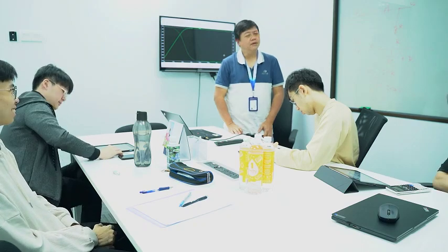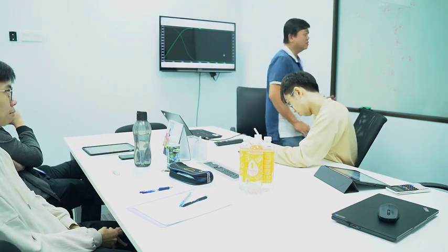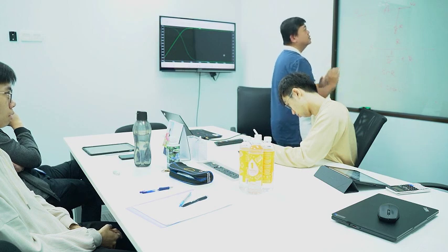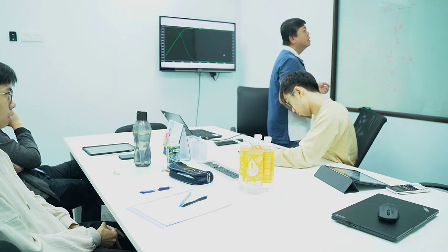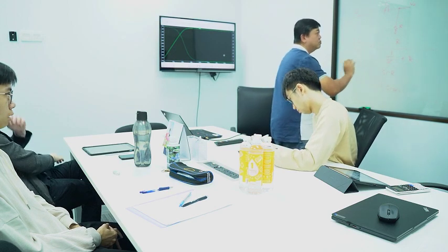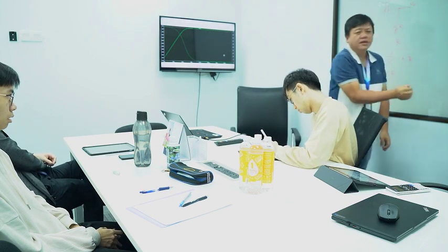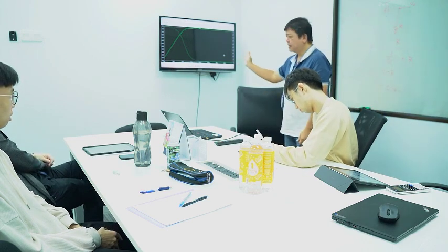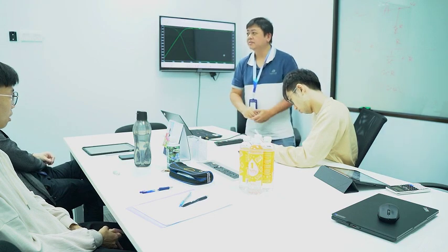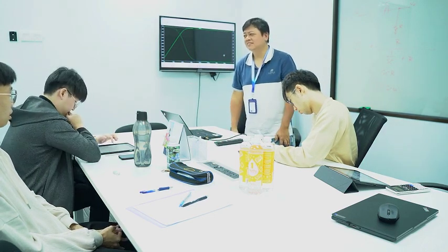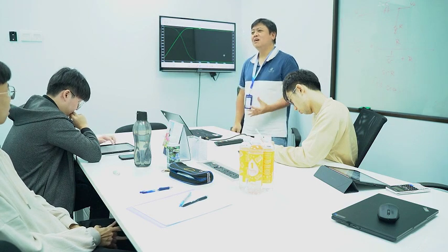But when you learn based on understanding, you derive the formula. After that, you know that a high pass filter has one zero and one pole, and you prove it by the curve; you can draw the curve theoretically. After that, you can do a simulation to see exactly what happened. I tell you, next year you can still remember it. So this is a powerful way to learn things.